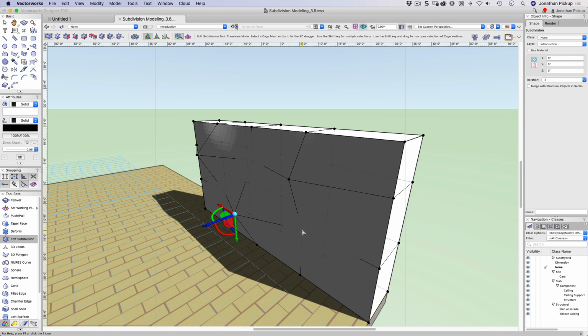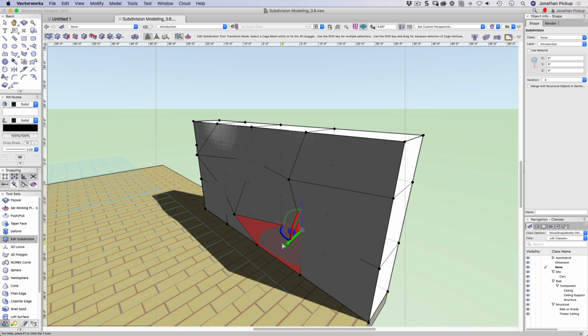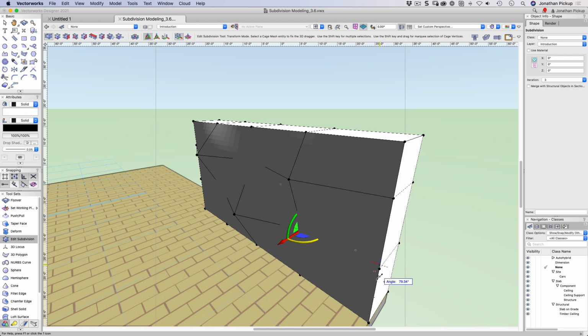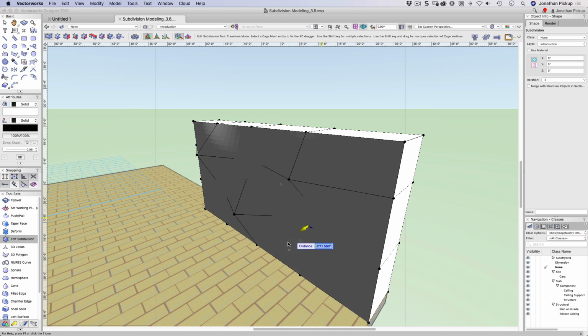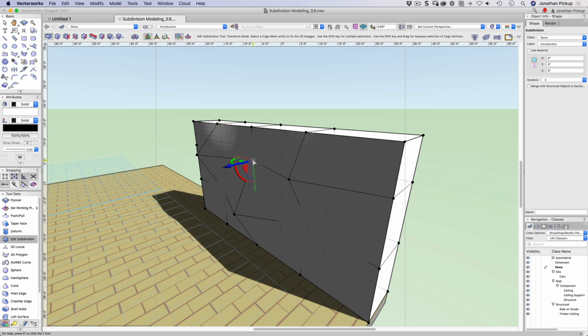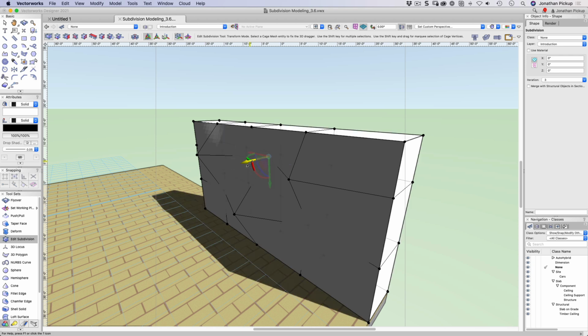Now the dots that go in, you'll notice that when I click on the dot, it's actually rotated. I'm going to grab hold of this protractor, and I'm going to pull it up to the top dot there, and that'll give me a good spot, or at least it's rotated that. This one here, grab hold of that, rotate out to this dot. So now this is square to my object. So now I can push this in, hold down the back quote key again. Just got to get rid of that. Hold down the back quote key, push that in and click. This one here, grab hold of that, hold down the back quote key, push that in and click.